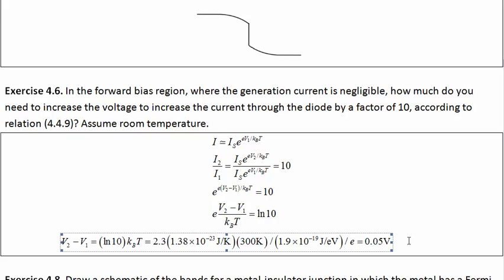Then around that voltage, you're not going to need much additional voltage to get current, and the diode is behaving like a free pass for current as long as it's trying to go in that direction. You do need some forward bias voltage to make it start conducting, though, because the bands need to be aligned.